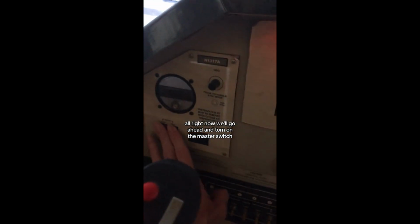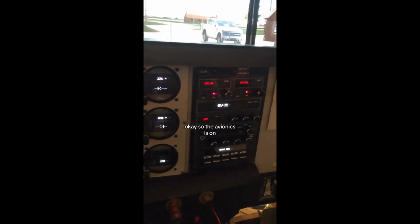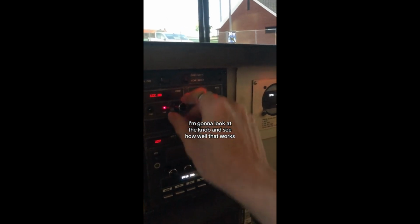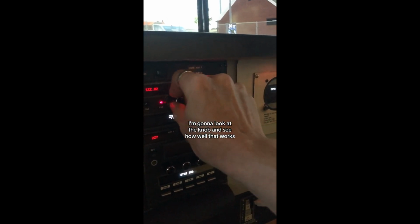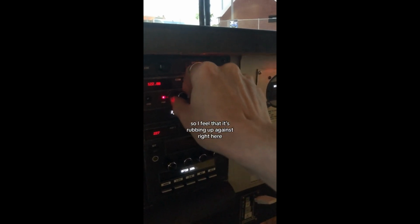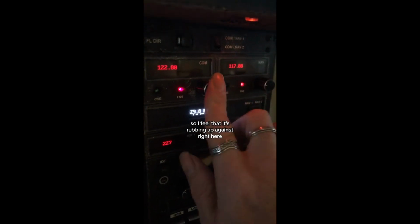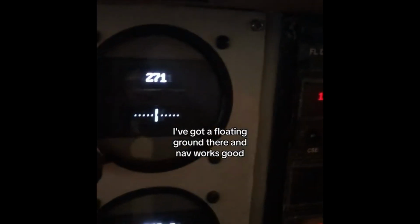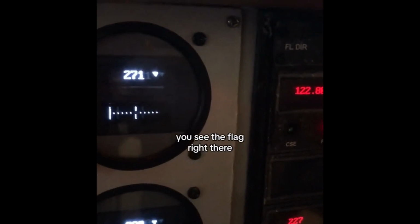All right, now we'll go ahead and turn on the master switch and the avionics. Okay, so the avionics is on. So we're just going to test a few things here. I'm going to look at the knob and see how well that works. So I feel that it's rubbing up against right here. Oh, I've got a floating ground there. And nav works good. You see the flag right there.